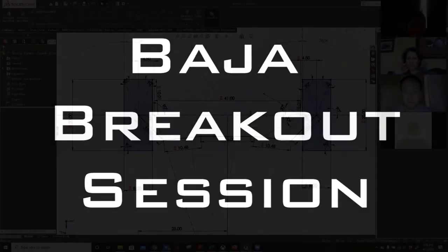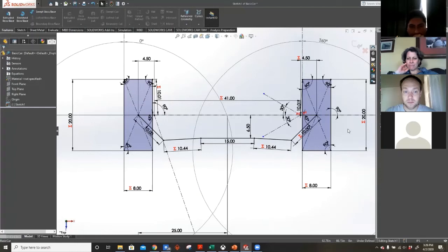So what's limiting us right now, Aaron? Basically what Aaron's doing is he moved the connection point further from the steering axis. The hard part about that is you have to travel further to get the tight turning, because if it's down here, the radius is smaller, so you can get more turning. But he's also made the rack shorter and pushed it down. He's still keeping close to Ackerman geometry, so he's keeping his meeting point along this point.